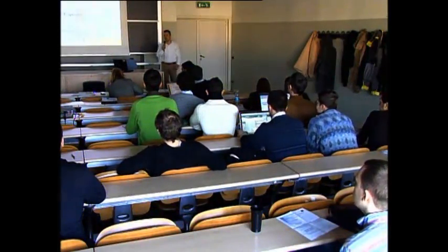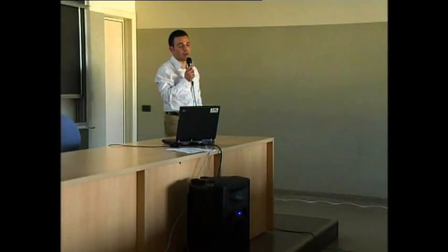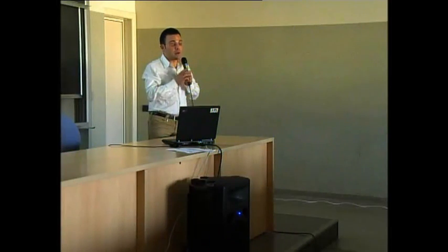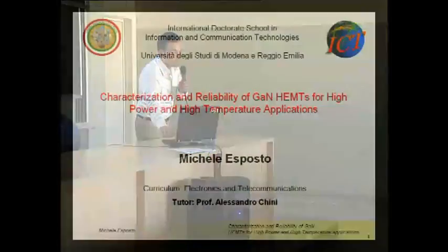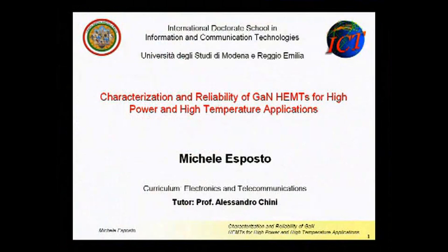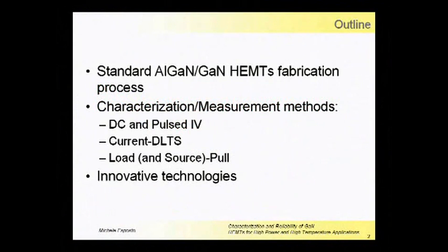My presentation is about the characterization and reliability of gallium nitride HEMTs for high power and high temperature applications. My talk will focus on the standard AlGaN/GaN HEMT structure and its fabrication process, on the measurement methods employed, and the innovative technologies under investigation.